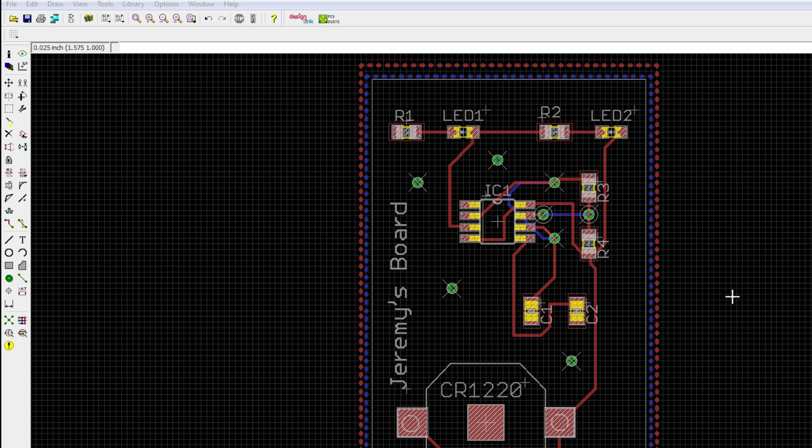Each file that it outputs represents a different layer on the board. One is the top copper, one is the bottom copper. You have your silk screen, which is what your text is written on, and your solder mask and your drill layers. For more complicated boards, you might have multiple internal layers. You might have a paste layer that defines where to automatically put down solder paste if you're having your board assembled as well. But we're going to keep it pretty simple here.